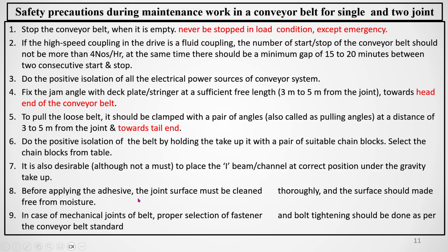Before applying the adhesive, the joint surface must be clean. The joint which you are going to repair, you have to clean it first thoroughly, and the surface should be made free from moisture, and sunny weather should be there. There should not be rainy weather or moisture. So there should not be any moisture on the surface.